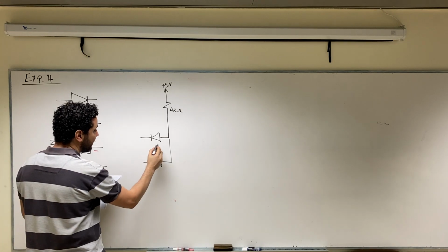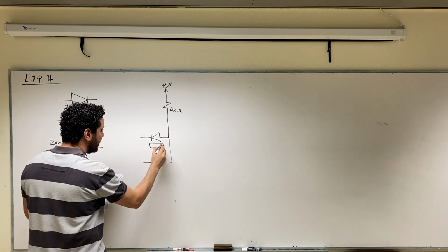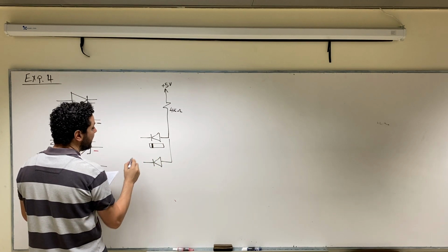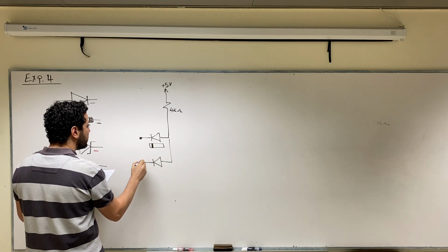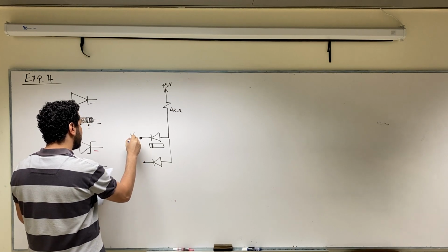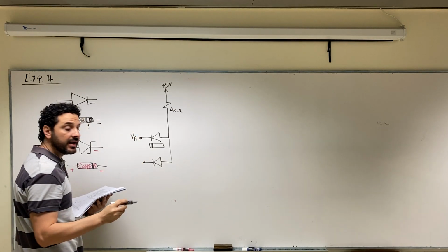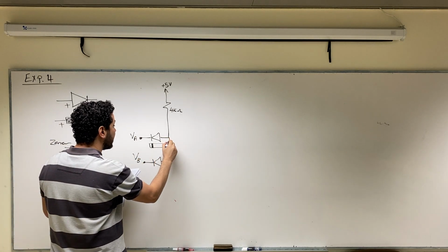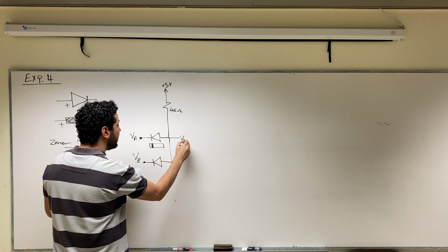Of course, in the lab components you have to connect the regular diode with the silver line in this side. Okay, we are going here to connect 2 voltages, VA to this terminal and VB to this terminal, and we are going to measure the output from here.